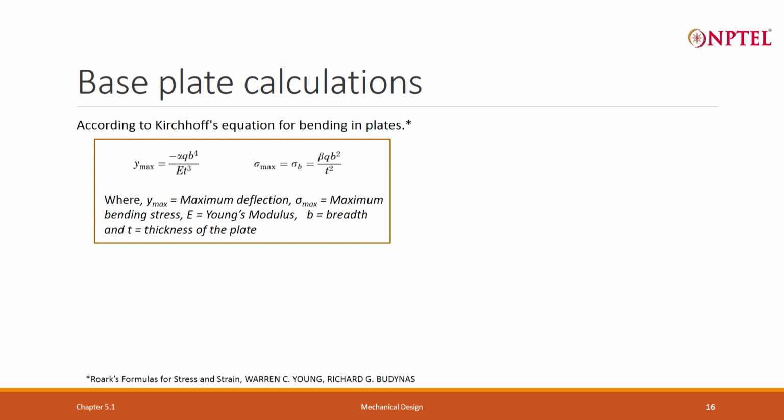There is an equation, the Kirchhoff equation, that is a fourth order partial differential equation. Either we can solve it with the boundary conditions, or there is another way of doing that. We use the direct formulas from a design data book.